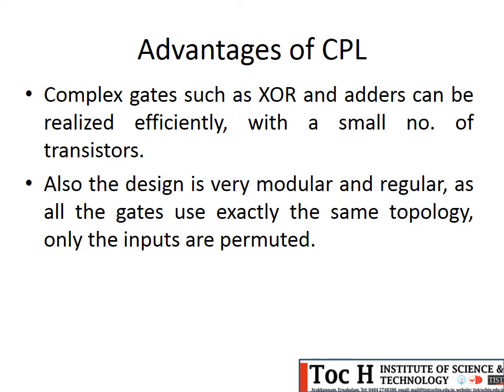So if we wisely give the input signals and the control signals, we can realize any function, and that is the beauty of CPL. The design is very modular and regular, as all the gates use exactly the same topology. Also, complex gates such as XOR and adders can be realized efficiently with a small number of transistors.